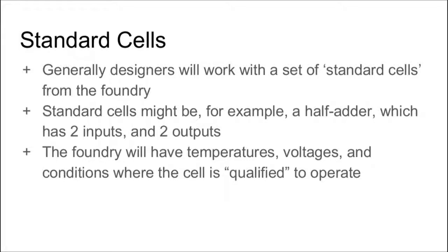If you know that you are going to be running things at low voltage, for example, most foundry cells will be qualified at around 0.6 volts. Bitfury, I believe, runs their chips at 0.27 volts. You can't use the foundry standard cells anymore. You have to make your own. And so you can actually take these XOR gates, and at this level you are taking physical features of the chip. You're talking about fin distances and other really physical stuff, and you're running simulations that are trying to emulate physics to optimize your gates.